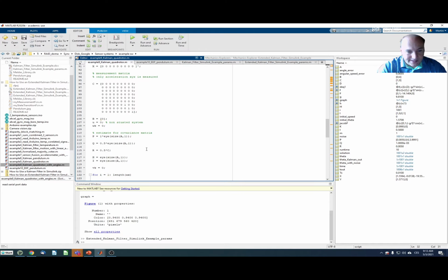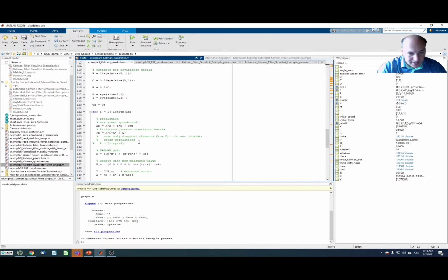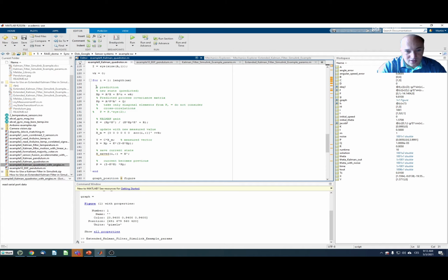And then I will just make an estimate of some variable b, which in my case I do not estimate any power from the motor, so I do not have anything in the matrix B. And I make some estimate of my covariance matrices, which we will see today also how to make this estimation. And then it's all the way to the Kalman filter.